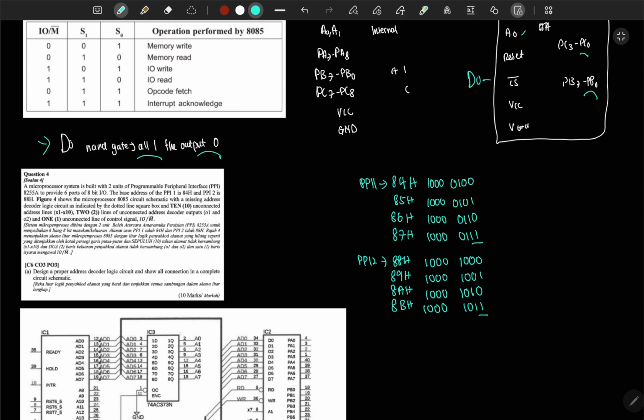Before we begin, if we notice here, they have mentioned 2, 5, 6, 9, 12, 15, 16. What they are trying to tell us is this is A0, this is A1, this is A2, this is A3. The pin arrangement that they have given in the bits are A7, A6, A5, A4, A3, A2, A1, A0. So strangely, what we can see here is that for the control, A0 and A1 are being controlled. So immediately we assign A0, A1 to the chip.